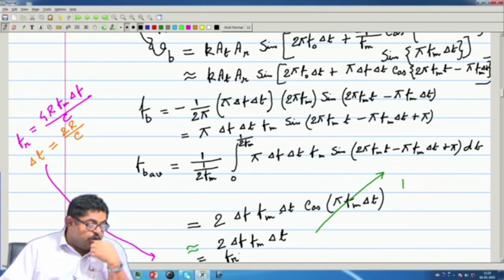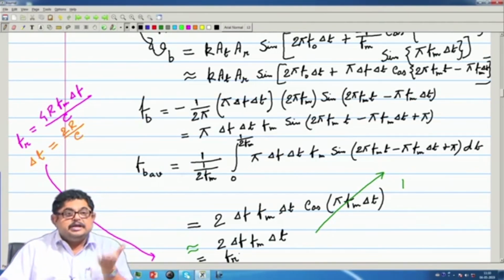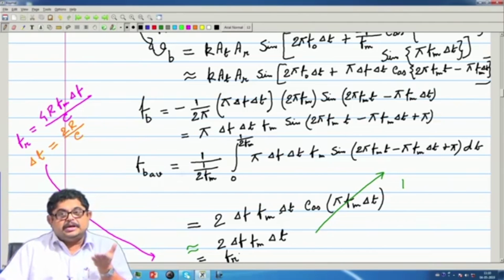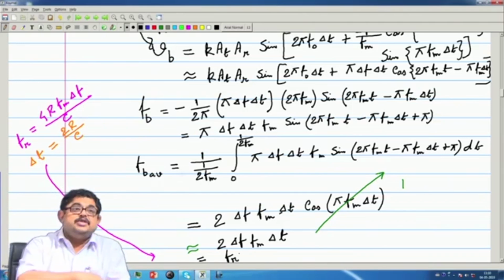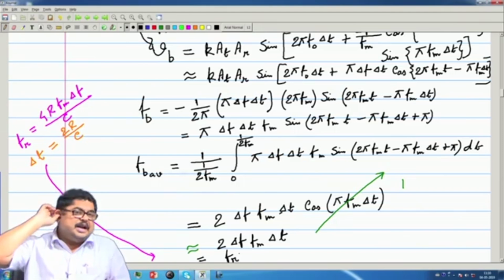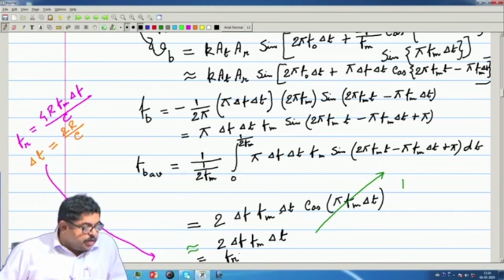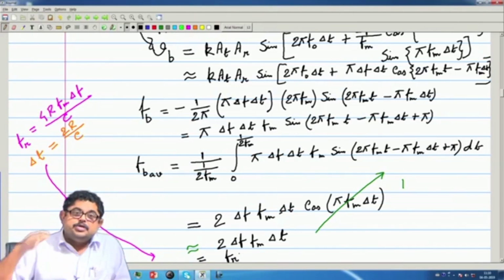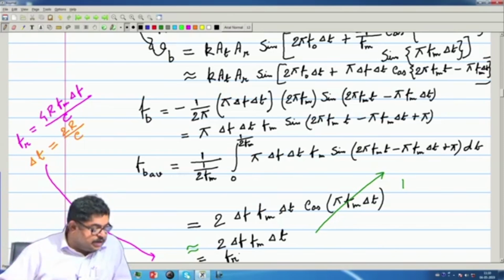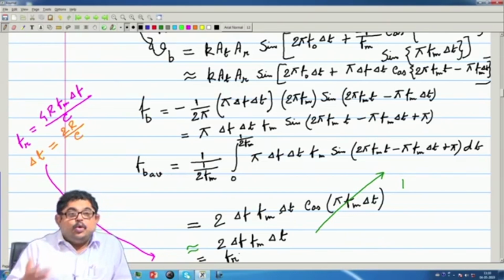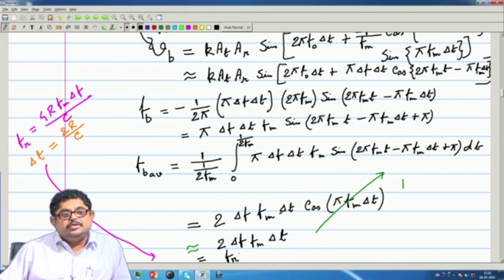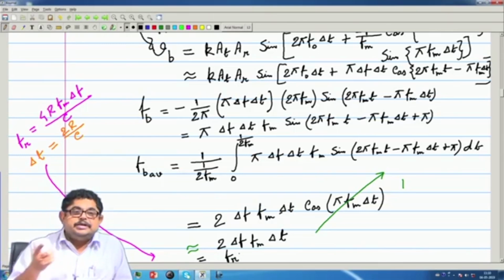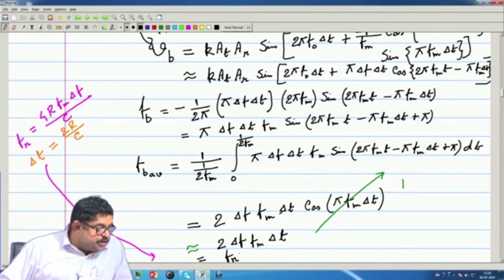Now, the Doppler is small because the radial velocity of the target with respect to the radar, that means the change of the velocity of the radar, is not much. So, Doppler is neglected, and it is assumed to be a stationary target. Also, here there are no clutters. Generally, ground is a good source of clutter, but here ground is the target, so no question of much clutter.